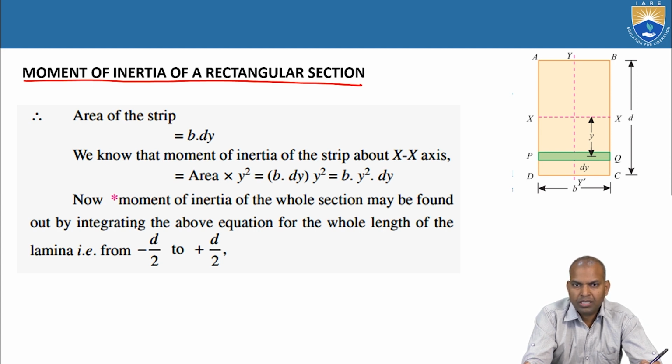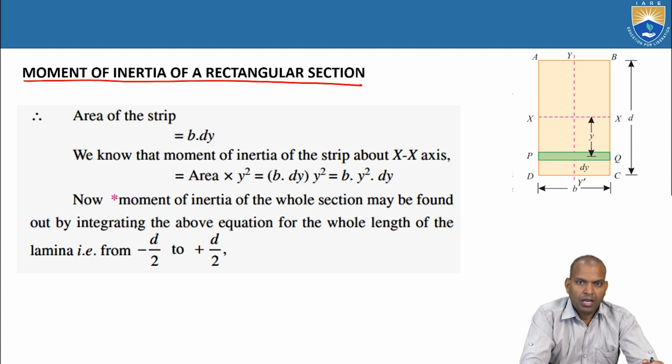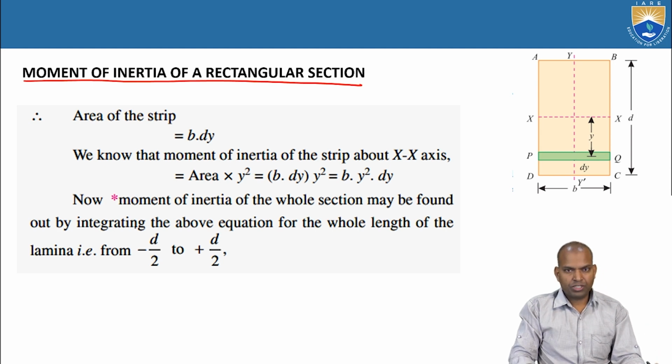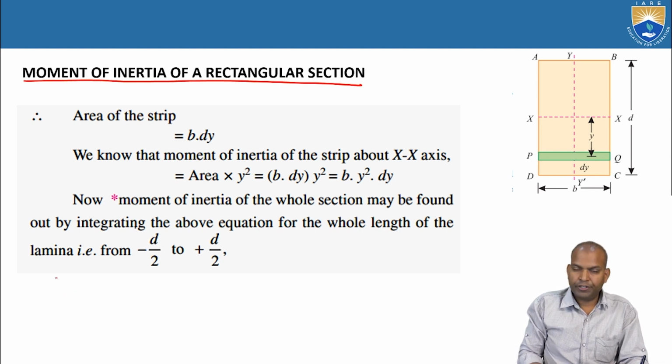Also the shear stress distribution across the cross section of the beams. And also by using this moment of inertia concept, we can calculate the span of the beams, and moment of inertia is also useful to find the strength of the beams, that is the section modulus. Let us give a glimpse of how this concept will be useful. Here the moment of inertia we are talking about is the area moment of inertia, not the mass moment of inertia.